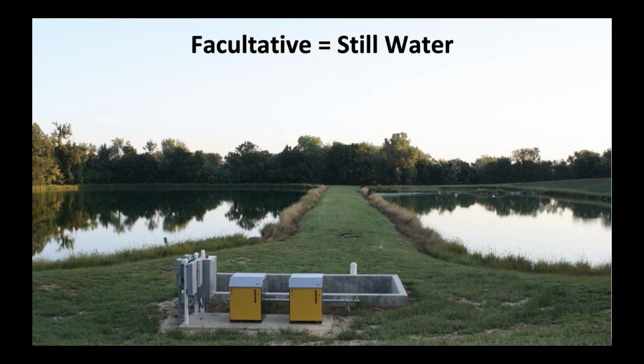So facultative, going back to our upgrade facility. Facultative lagoons are basically lagoons that tend to be very large relative to their flow and relatively shallow. So you're looking at about a 3 to 5 foot depth. What it's relying upon is a very long treatment time, about 120 days within a facultative lagoon system. The water comes in, you get oxygen transfer at the surface of the lagoon that helps to create a little bit of mixing, helps to add a little oxygen to the water, and you've got that anaerobic, anoxic, aerobic type of treatment across the whole system.